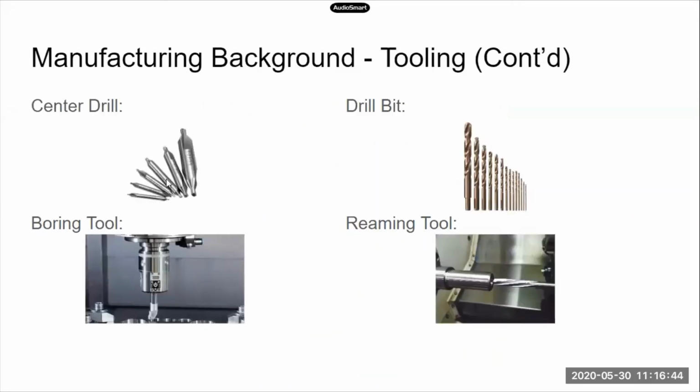All right, and then this is what the center drill looks like. I mentioned you may want to center drill before you actually drill. This is just to keep it centered. Drill bits, there are some drill bits that are not fit for metal, mainly because they're more designed for wood or softer material like that. As you can see, they come in a bunch of different sizes. There are different sizing groups, like metric.